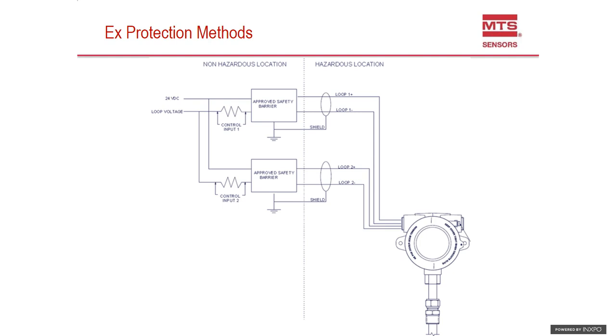So you need to make sure all those things are done and matched up correctly, and for the most part, the intrinsically safe installations require a lot more design work. They're easier to physically install because you don't have all the explosion-proof components, but there's a lot more thinking that has to go on at the beginning to make sure everything's matched up.